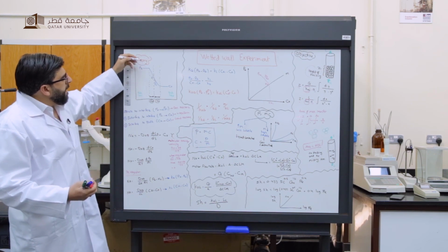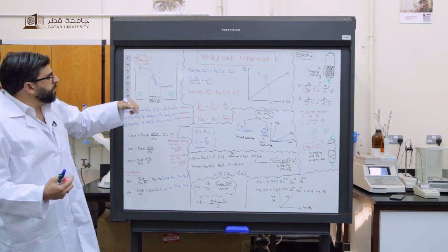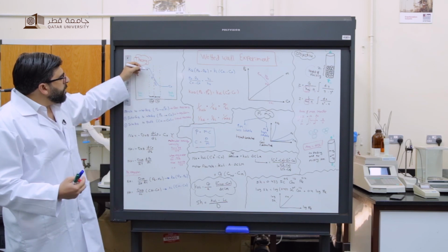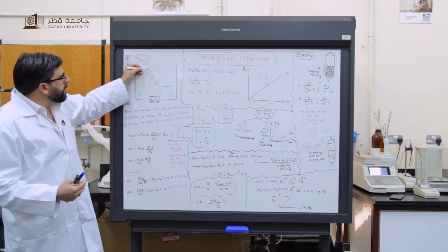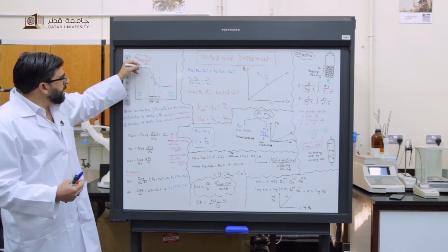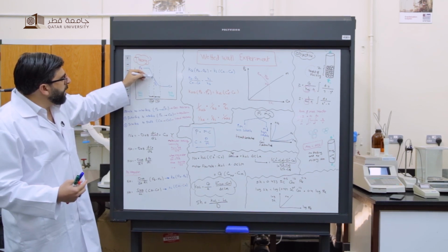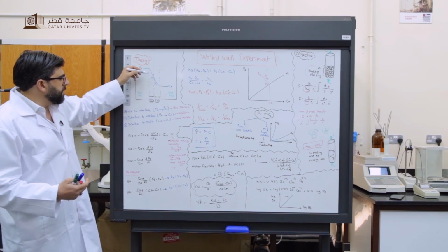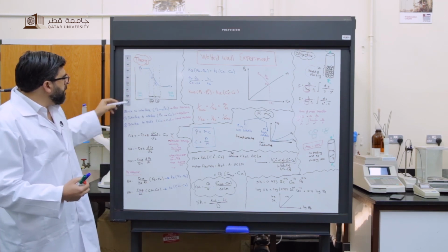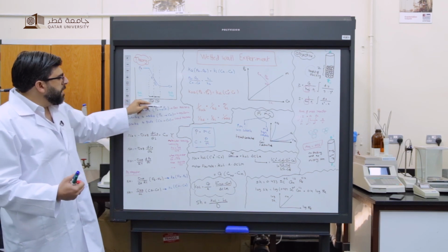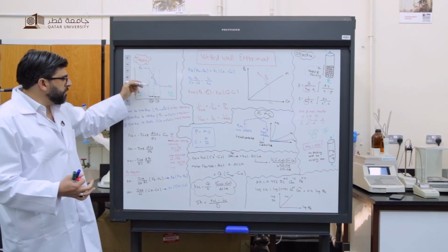When it is mass transferred into the liquid through the interface, there is some resistance in the gas bulk, so the amount of gas decreases a little bit until it reaches the interface because of the gas resistance. This is the first step: from the bulk to the interface, we have some gas resistance.